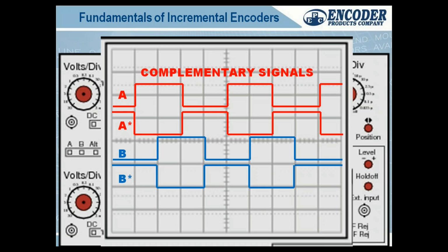You need to make sure, especially with IP ratings, that you're choosing the appropriate housing for the job. I just worked on another train application, and the encoders were failing up in the Arctic, inspecting railroad track cracks. That's why it's on my mind. That one was because the encoder they spec'd was IP50. So they were getting condensation, and then the condensation was freezing, and it was actually cracking the glass on the photosensor. So we've since changed that out to an IP67 encoder for them. There's nothing about preventive maintenance that you can do once it's designed in. It's just why it's critical to choose the right package in the beginning.